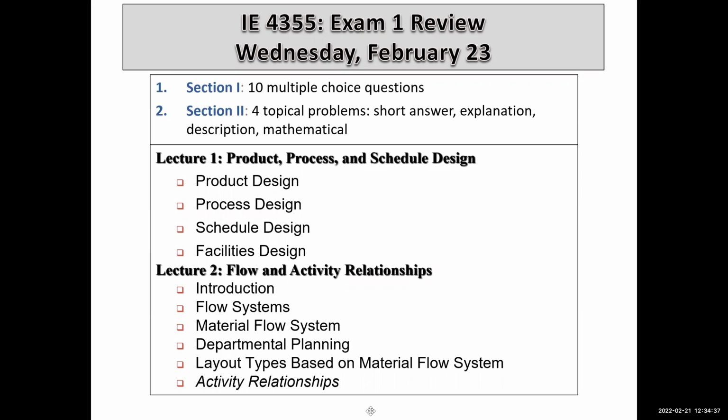decision-making process in terms of deciding how you are going to solve a conflict, you're going to have to tell me, okay, this is what I'm going to do, and this is how I'm going to split the cells, and I'm going to purchase a second machine, and I'm going to put one machine in one cell and one machine in the other cell. Or I'm going to be sharing that single machine. I'm going to put that in the middle, and I'm going to be creating 2 cells. So those are the types of questions that you should expect in addition to solving the problem.